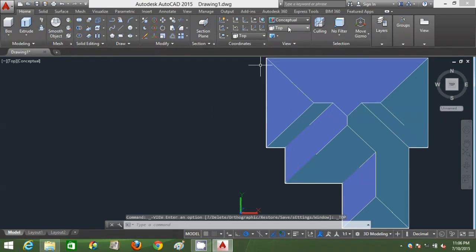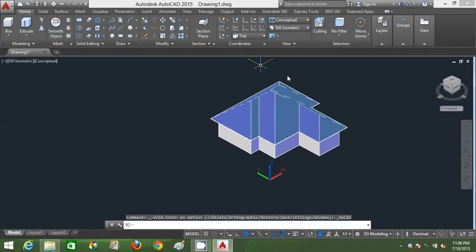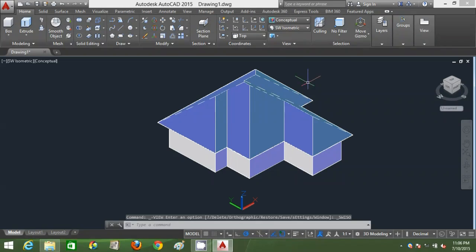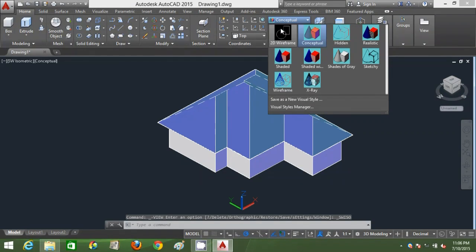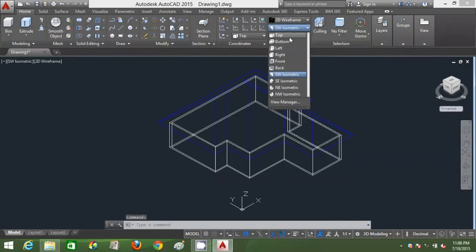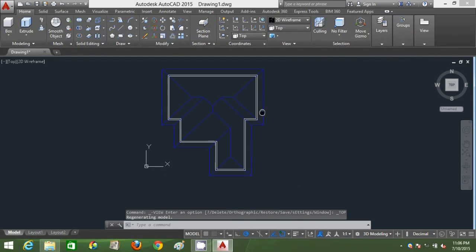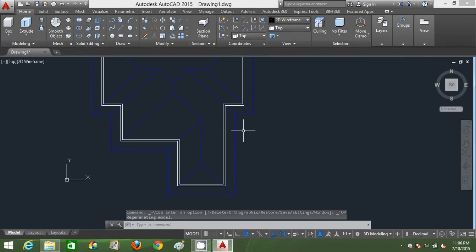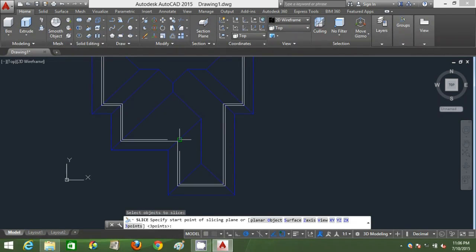So you can actually 3D orbit your view by holding on your shift key from your keyboard and by dragging your scroll key from your mouse. Alright, and you can just automatically 3D orbit your view without clicking on the view cube, without using view cube.